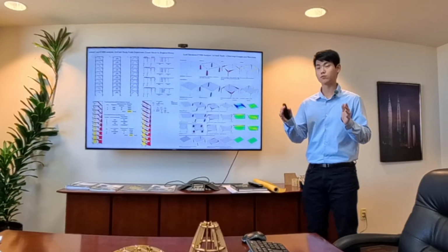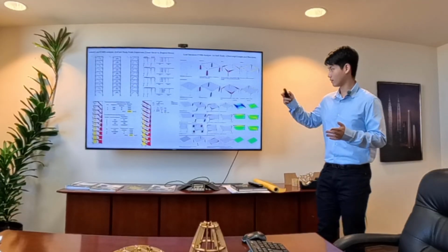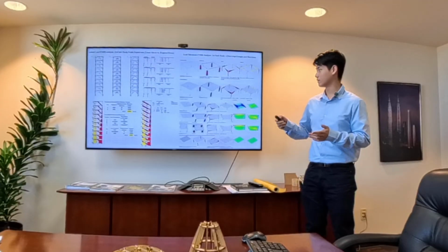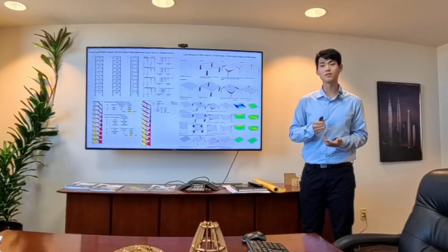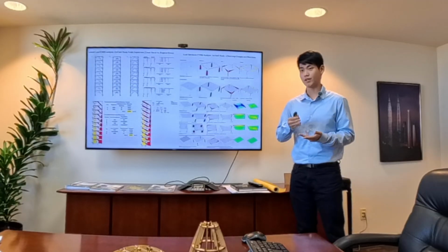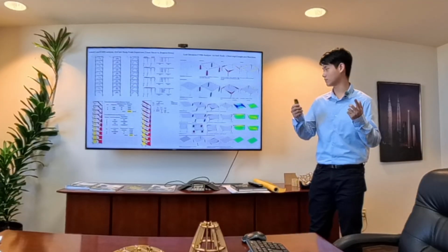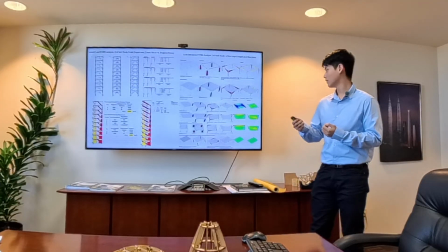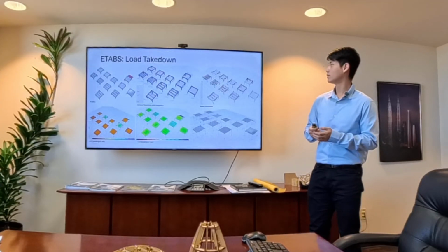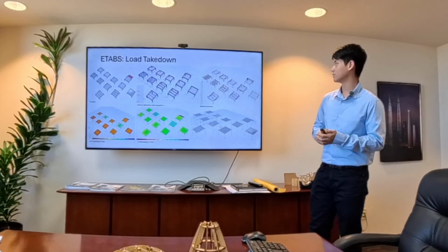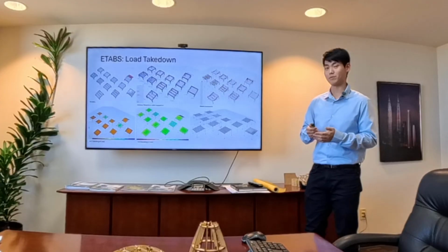For my third self-study, I moved on to simpler 3D structures. It's just a basic frame structure with 4 beams and 4 columns, and through an iterative comparison, I looked at the effects of changing the slabs, the decks, and the connections, pin versus moment, observing how axial moments and stress distributions are affected when changing those values. These are all the studies I did, looking at the bending, moments, and deformations.